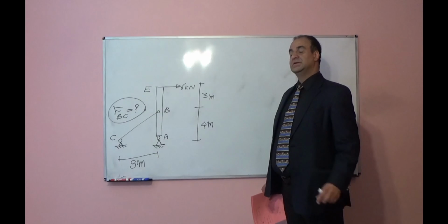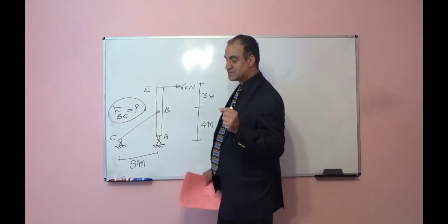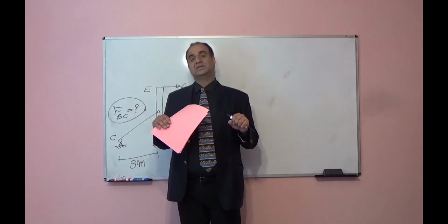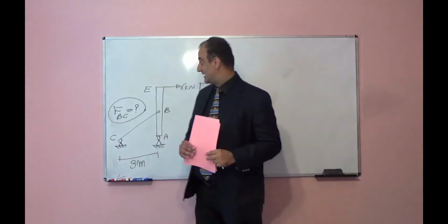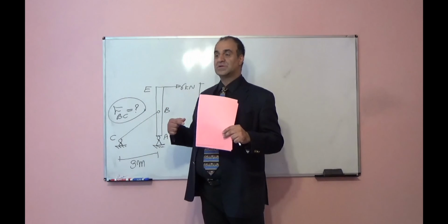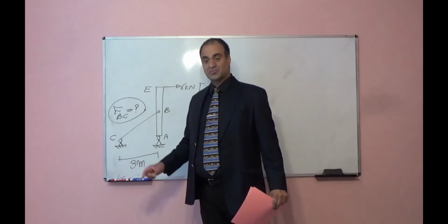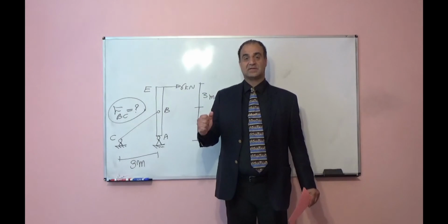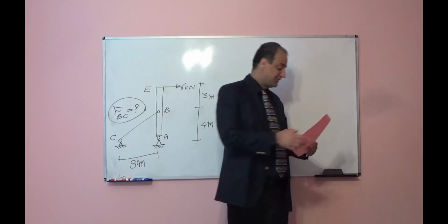It is clear, inside of the cable we will have only axial force. Cable, it is a structure. It cannot sustain bending moment. No resistance against bending moment. No resistance against shear force. It can only sustain axial force. And you cannot even apply compression force. You can apply only tension to the cable or rope. So cable or rope will resist only axial force, and that axial force should be tensile force. It works in tension only. Find that tension force.